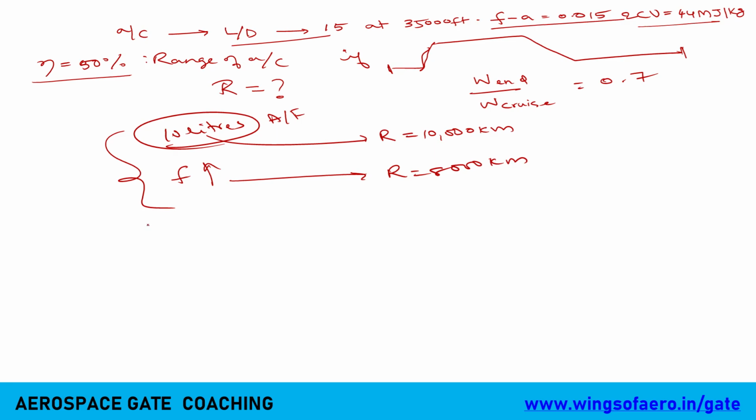So what does an engineer have to do? What are the possible modifications you will make to improve the fuel efficiency? Which component will you give more focus to, to improve the efficiency? I am asking about specific fuel consumption, and which component, like which engine component, will you focus on? Turbine. Okay, any other answer? Compressor, ma'am. We have compressor. Okay, any other? Combustion chamber, because of the heat input.